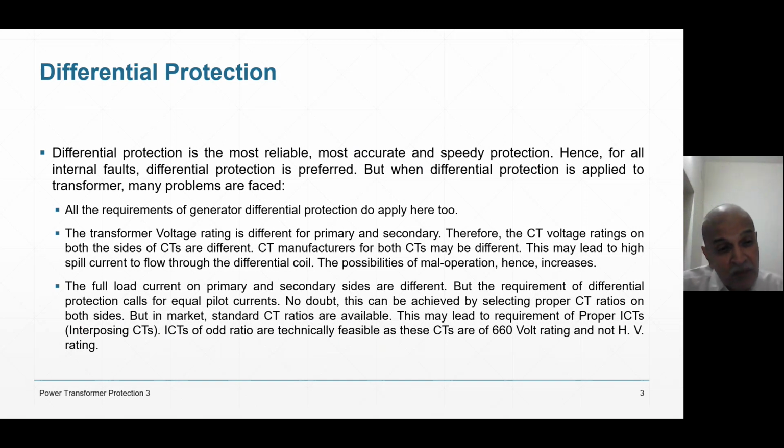But if I have got a 15.75 to 220 kV transformer, then on 15.75 I have got the current 9050 ampere. And on secondary side I have got some 601.16 or something, or 656 ampere or something.